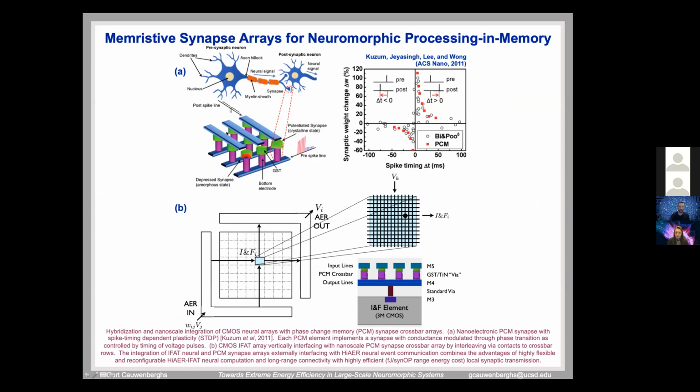Now, rather than each memory element being sequentially accessed as in digital memory, each element is doing the compute right there. The multiply accumulate is happening there, right? You present inputs along rows here, and you get outputs along columns, or vice versa. And so you can get this massive vector matrix multiplication in one clock cycle. You get this entire matrix multiplied by the vector, because owing to Kirchhoff's current law, you get all this parallelism happening.